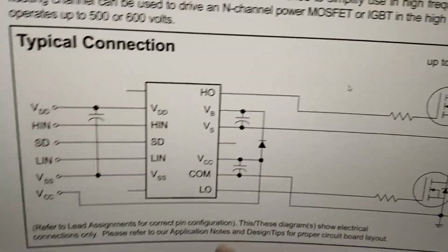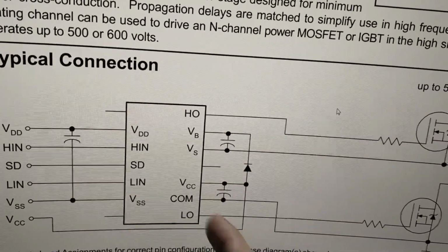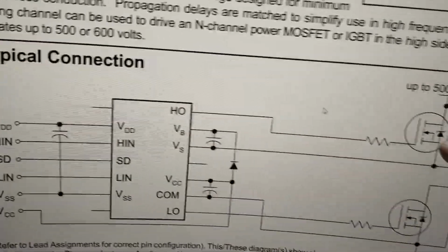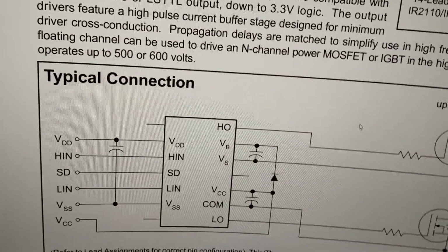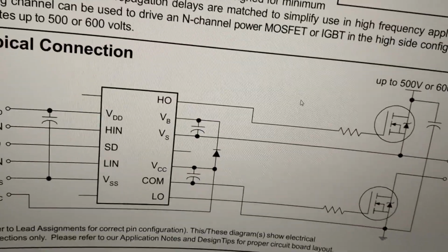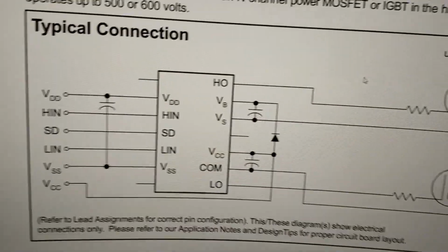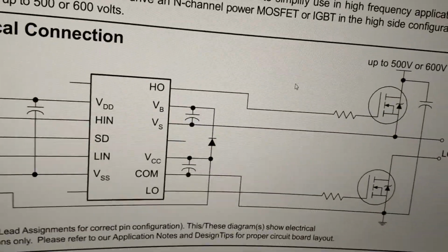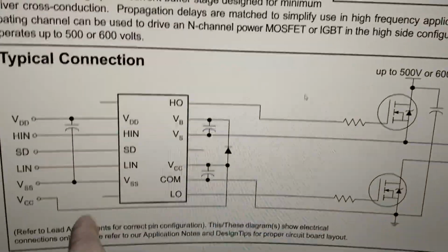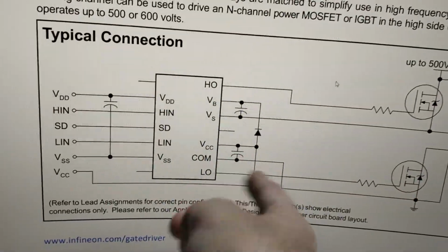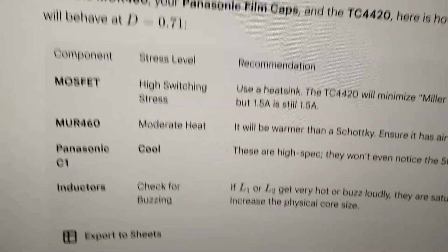And another thing is, since I talked about the high side, this basically uses a capacitor and creates a floating supply, so you can drive the high side. And you can still run this entire IC off a single supply. So if you use something like the TLP250 or TLP152, which is an optocoupler based driver, there you would need a floating supply, which would increase the number of DC supplies you would need. But in this case, since this creates an artificial supply of sorts, one supply is enough. So we're going to be using this. And yeah, let's just go into the circuit.